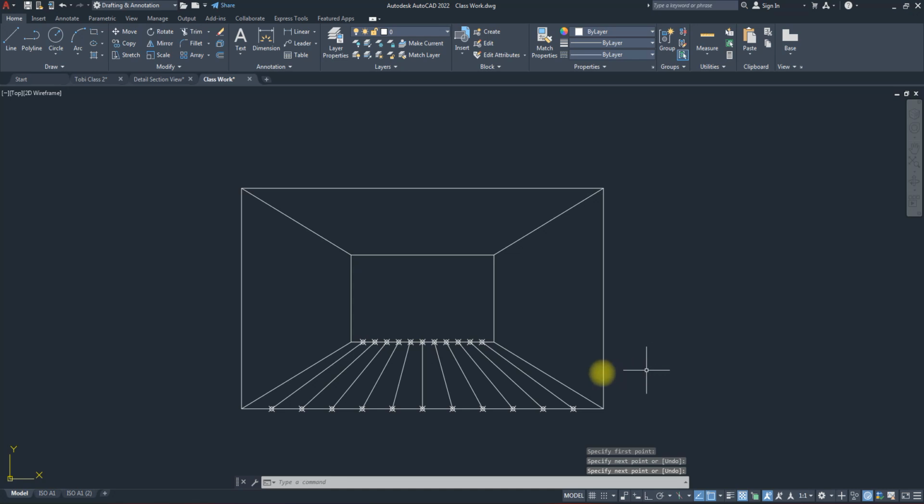All right. So now we need to also do this horizontally. That means you need to also subdivide this line. But in this case, since this line is equal to this line, I actually don't need to subdivide both of them. One of them is okay. I'll just draw a line all the way. So let's do our division and select the line we want to subdivide. So div for division, select this. Let's say we want to divide this into 8. So just say 8. So we have that subdivision.